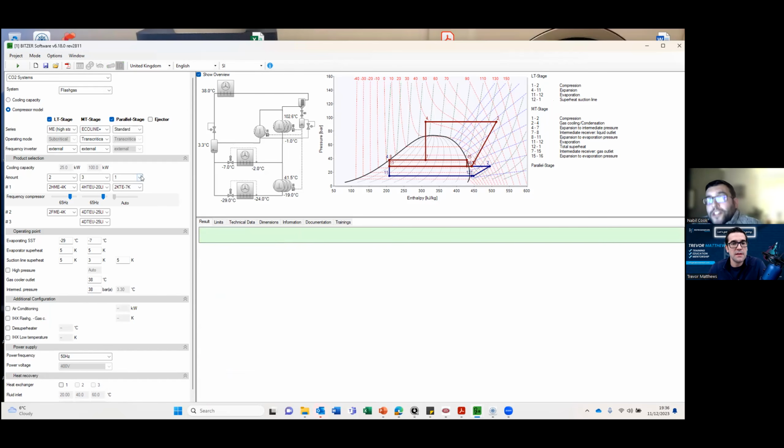Your first question is basically the same as the first question for the design of the other two suction groups. How many compressors are you willing to chuck at this? Exactly. I dare say the majority of systems of this size will not accept having more than one parallel compressor. They won't. Yeah. So we go cooling capacity again. Check that all our figures and selections are still appropriate. You'll see that for this one, an inverter is mandatory.